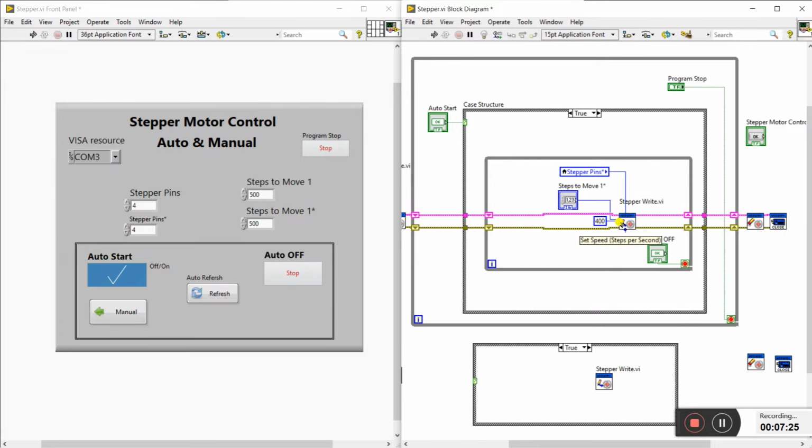Okay, now the last one is the set speed as per second. Okay, you can change the value per second, and I already declared 40. Sorry, I already declared the steps per second, in 1 second. Okay, we can say 1 second, and it comes with 100 acceleration. Okay, 400 speed moves the stepper motor. Okay, you can change it, but the limit is like 0 to 400 or 450 only. Okay, so that's why you need 300, 200, 100 like this.